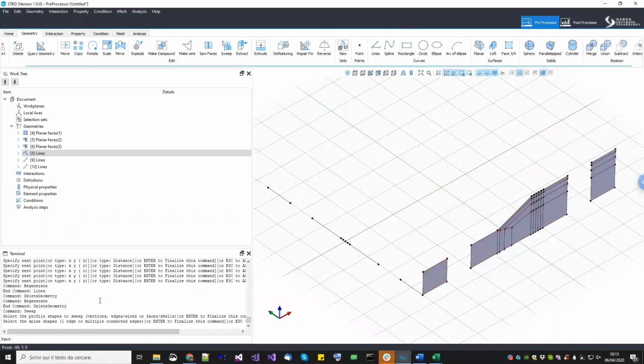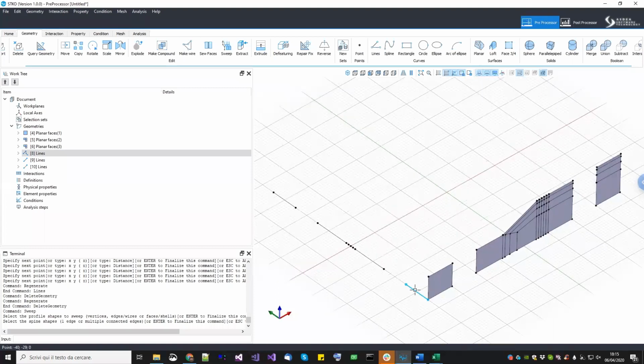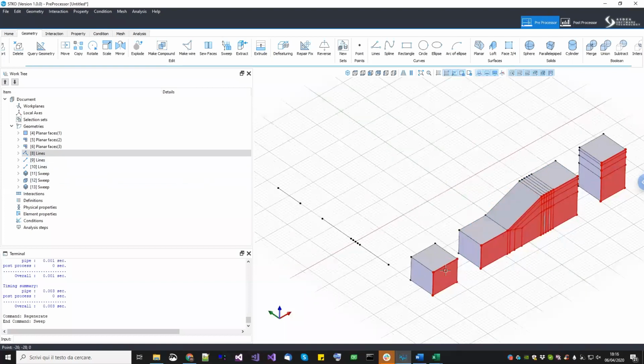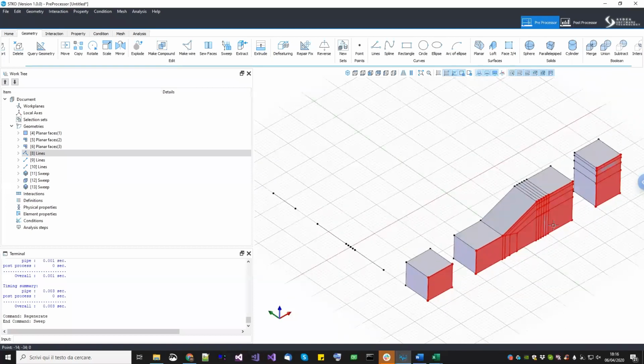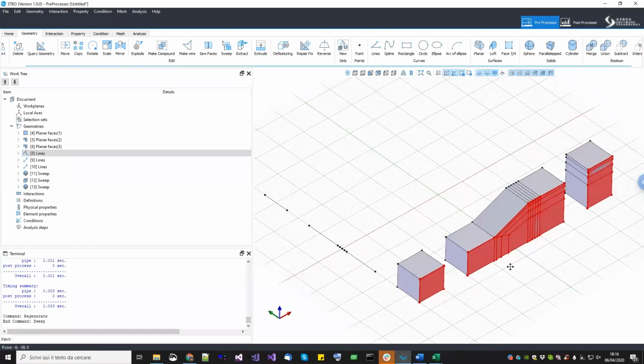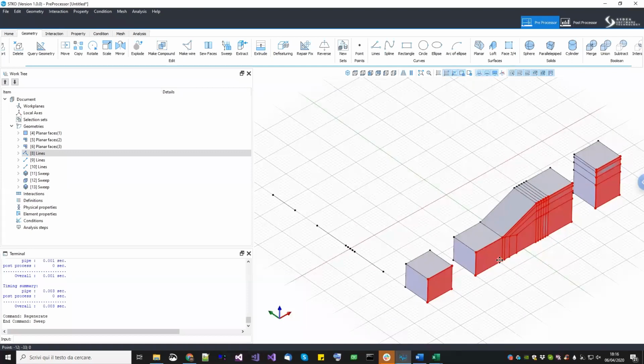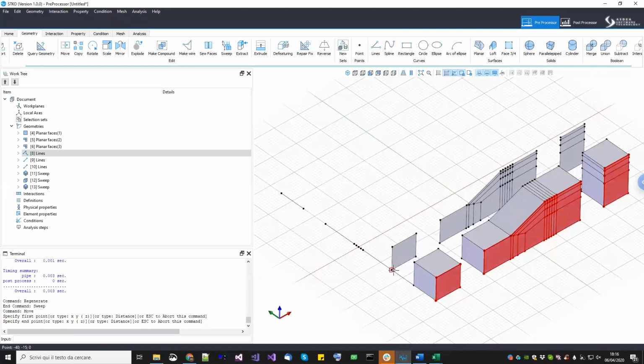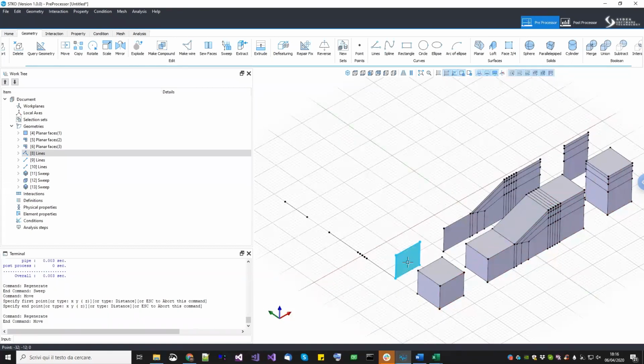Right click, and then, okay, now select the spine shapes. Spine is the extrusion profile. So first I want to extrude it along this spine, right click. And as you can see now, each face has created a series of solids. Now, for the sake of simplicity, STKO keeps the previous selection, because now I can either remove it or I can reuse it. In this case, I want to reuse it because I need these faces to do the next extrusion. So I can just click on move, and then I move the previous faces from this point to this point, so that I can select them once again.